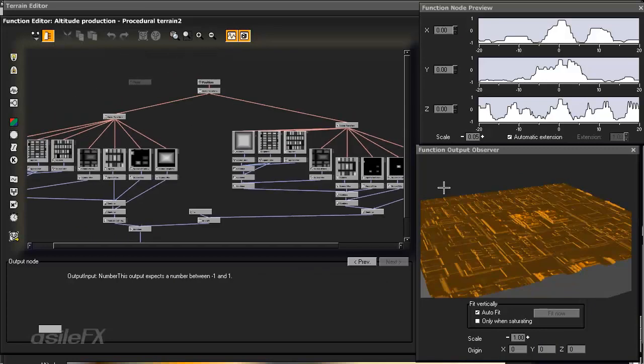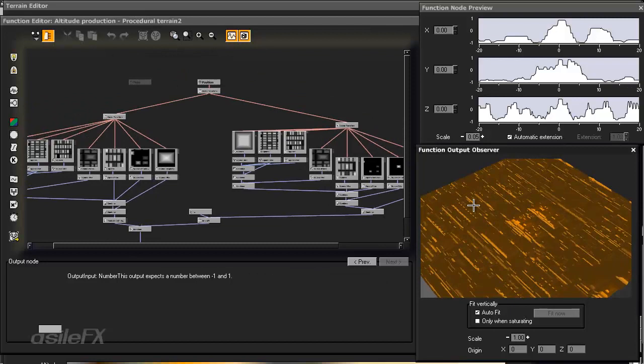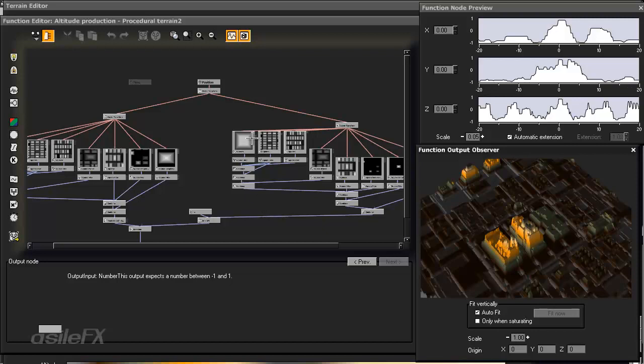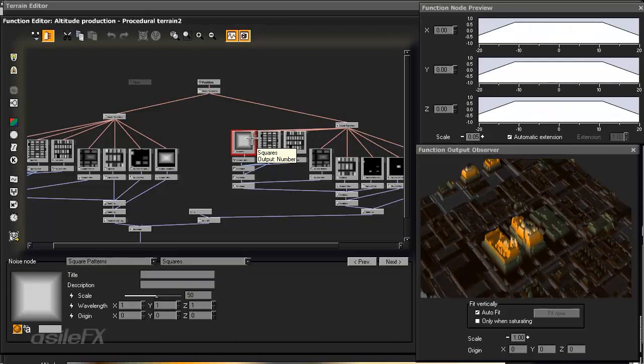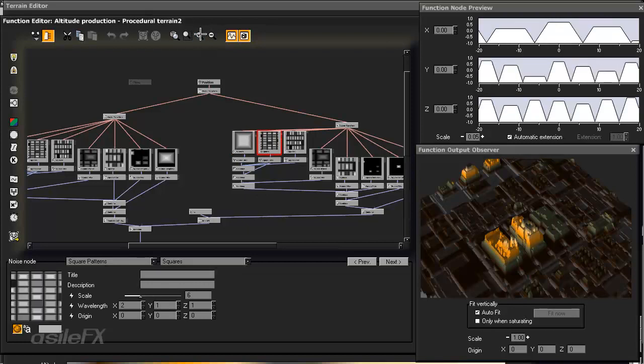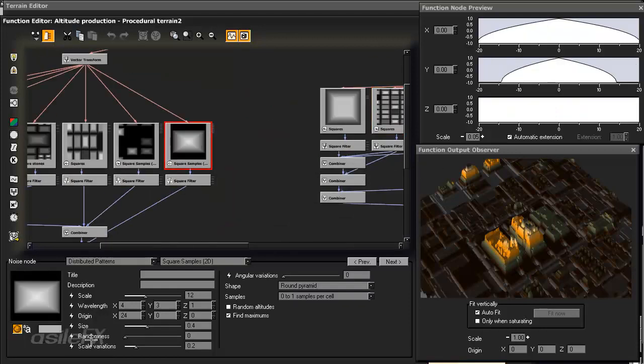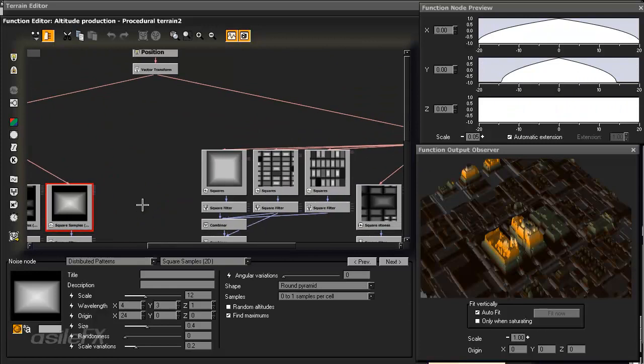Going into the function, there are a lot of vector manipulations we could do. Every single node and every noise that we have in here has the ability to extract its origin. Well, these origins can be manipulated with turbulence nodes. And a turbulence is a vector-based noise that will manipulate the vector. So if we wanted to individually manipulate any of these, we can pull out the origin and connect that.